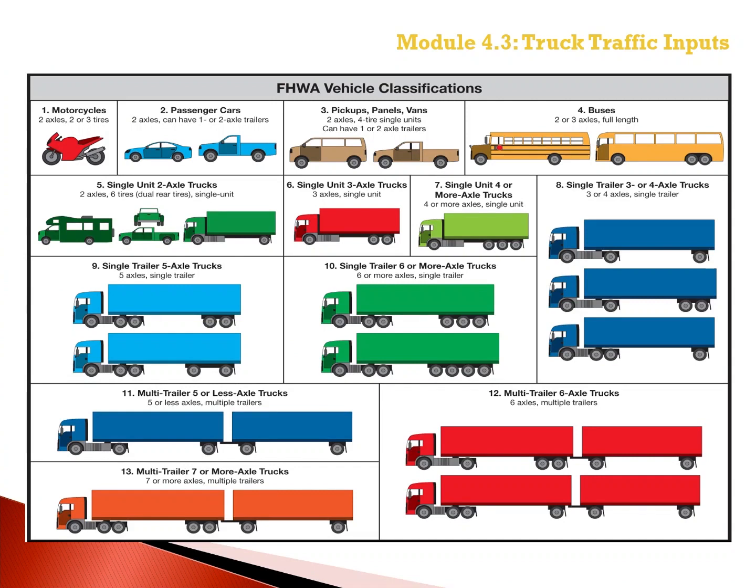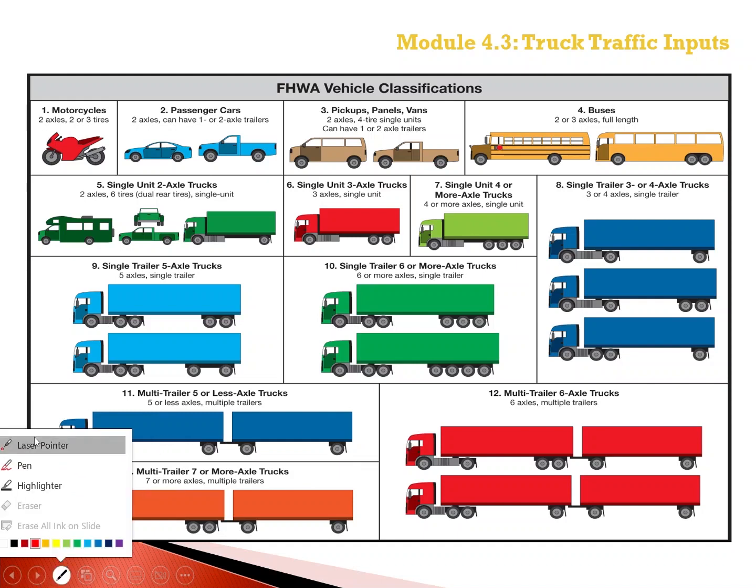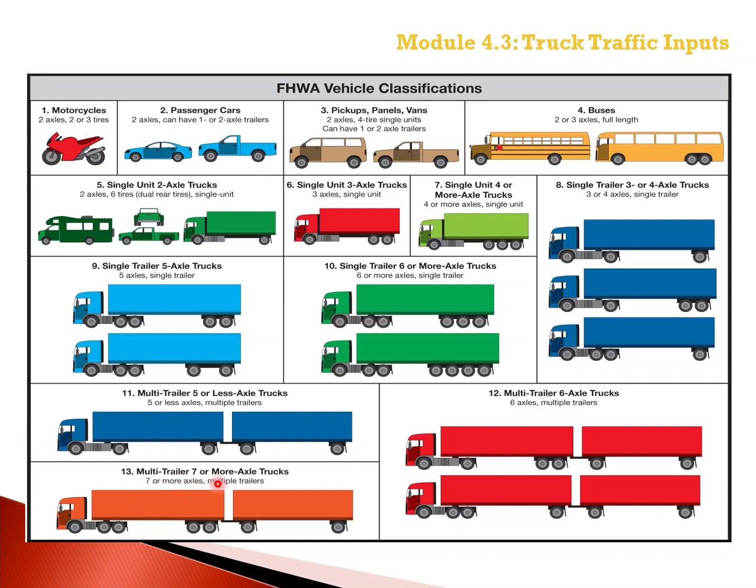The truck traffic and/or total traffic is defined in terms of the FHWA vehicle classification definitions, going from Class 1 motorcycles all the way up to Class 13, multi-trailer trucks with 7 or more axles. So from very light traffic to very heavy trucks.